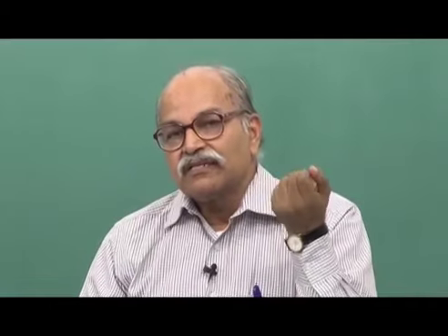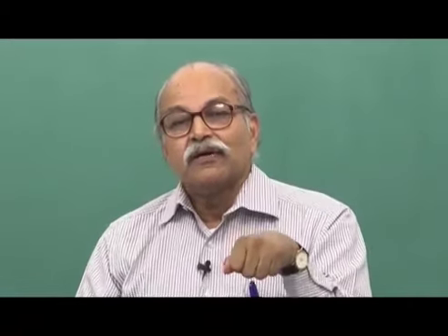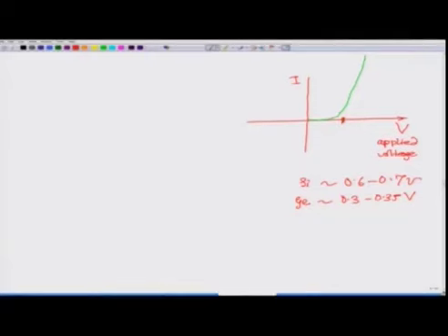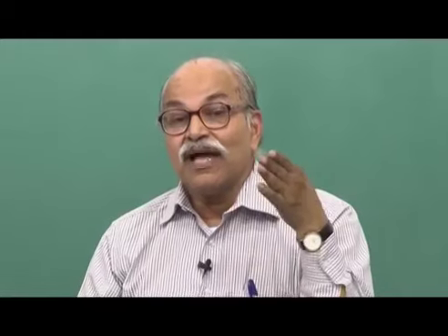If you have this PN junction diode and you apply an external voltage in forward bias condition, initially for small voltages, 0.2 volt, 0.3 volt, if you have silicon based semiconductor, you do not see any current, and after some 0.6, 0.7 volts, suddenly you see a lot of current going in. Now, for any PN junction diode, there is a limiting current which is the rating of that diode. If you increase current beyond that, you can damage it.